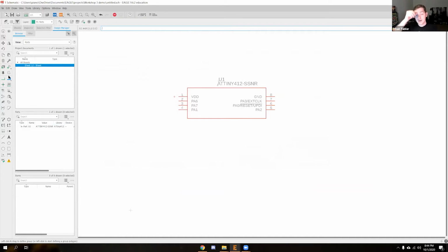So after I do this and explain some of the nets, I'm going to let you guys go off on your own for about 5 or 10 minutes to figure this out, because this is just the schematic building. We're not actually physically building the PCB yet. This is just the schematic, just so you guys know that. There are no parts right now on a board floating somewhere virtually. This is just a 2D representation of things. So one of the other really important tools is just this net button. You'll see it's a green...